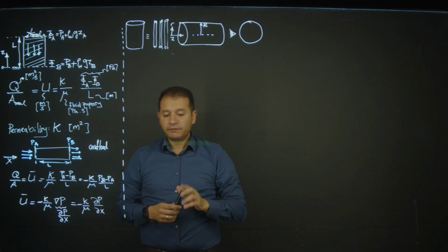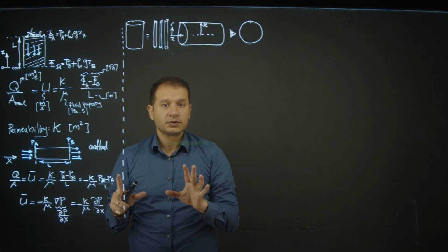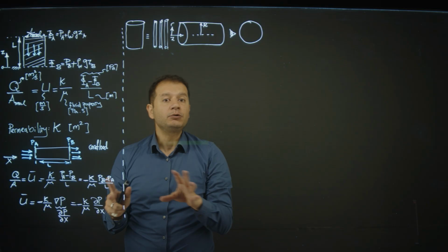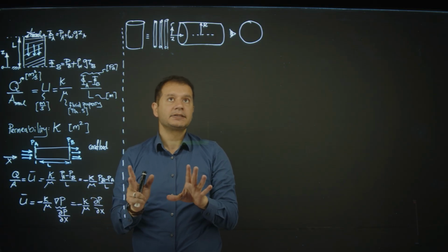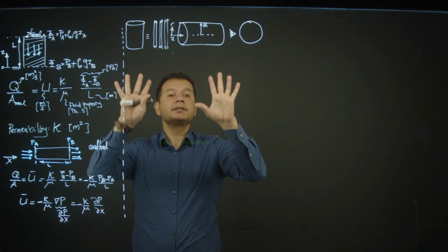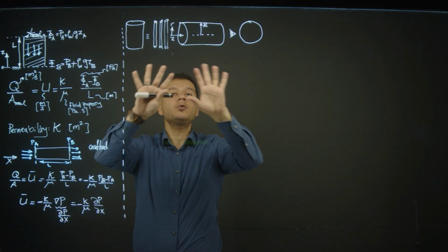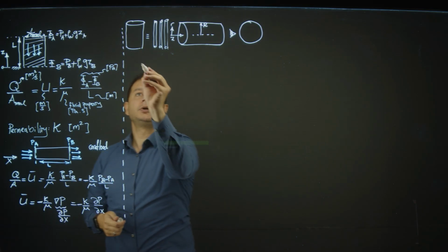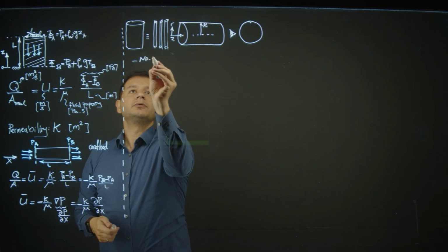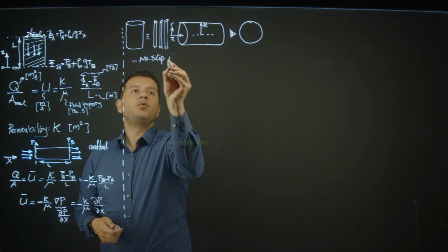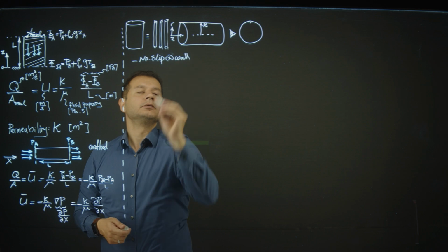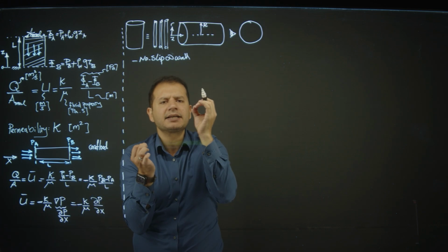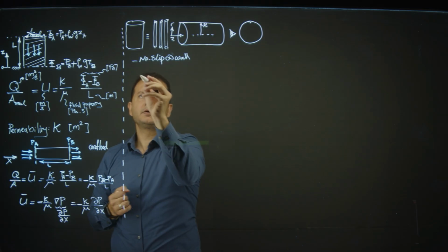Now, if I do the Navier-Stokes momentum balance and the continuity equation, which is mass balance, and apply certain assumptions that hold for this system that Darcy studied, what are they? No slip at the wall boundary. At the wall, the velocity should be zero. Fluid sticks to the roughness of the rock.